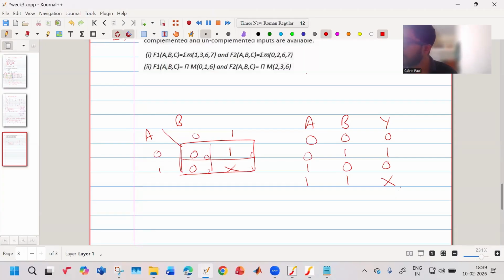So what that means is there could be a case where A and B both equal to 1 is not occurring. It will not even happen. Like an example of an SR latch or SR flip flop, where S and R both cannot be 1 at the same time. Then you don't have a properly defined output. You don't know what the exact output is.